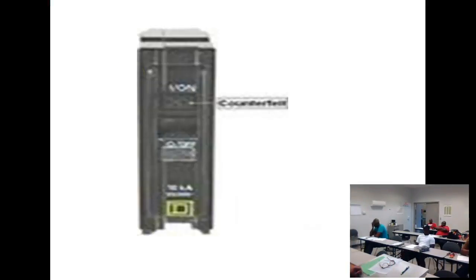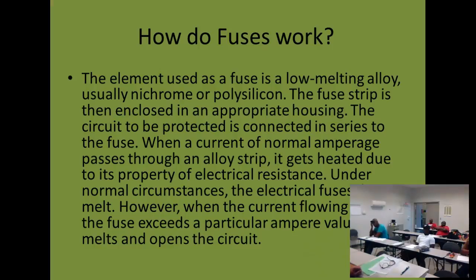You might run into a fuse. Okay, I got a couple up here. We've got cartridge fuses of different sizes, and screw-in fuses. Here's what we use on the furnaces. These are little car fuses. All a fuse is, is the simplest safety device there is, and it works off of an alloy that will melt at a certain temperature rating.